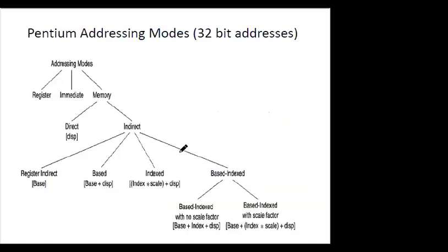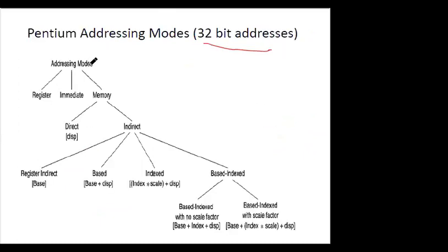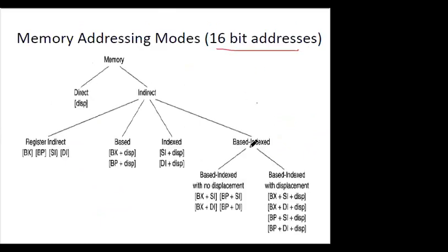So, we have studied two architectures, one is 32-bit, and the other is 8086, which is 16-bit. In the case of 8086, we need 16-bit addresses, whereas in the case of IA32, we need 32-bit addresses. So there is a difference between the address generation methods of these two. Memory addressing modes can be represented as direct and indirect, two methods.